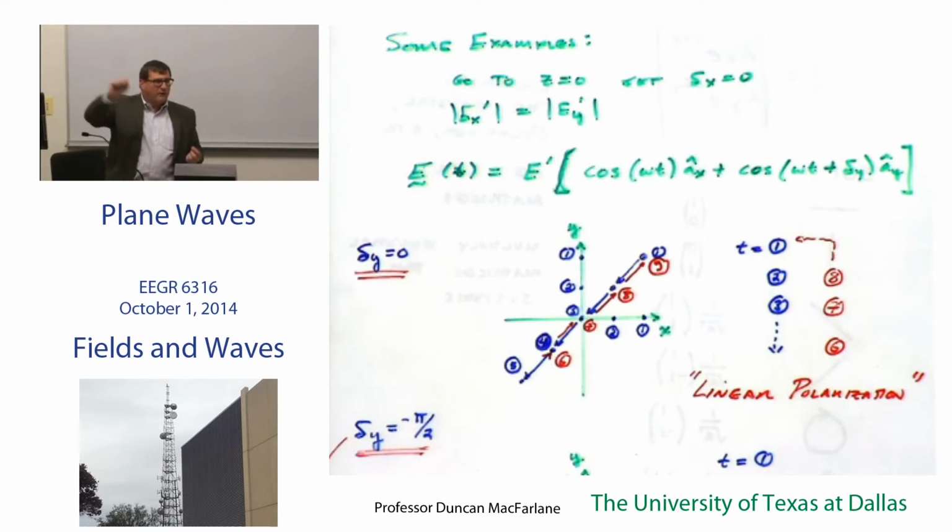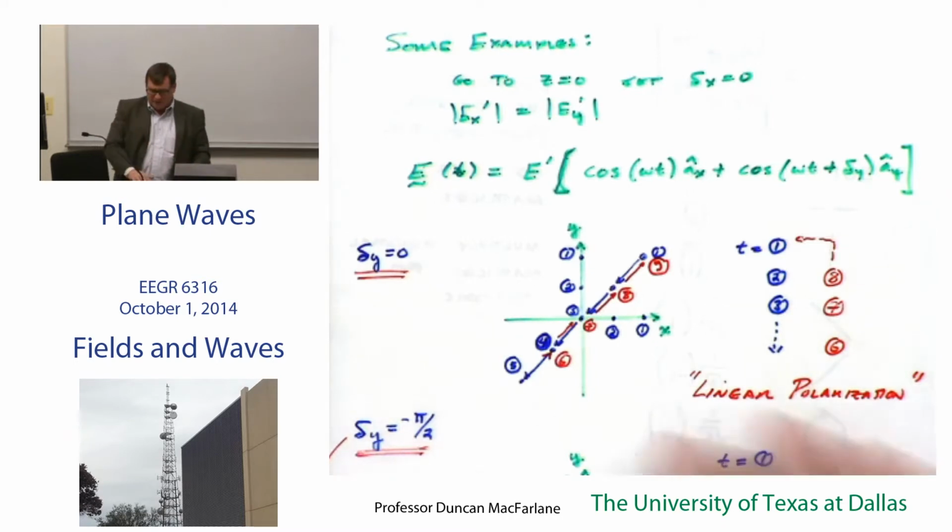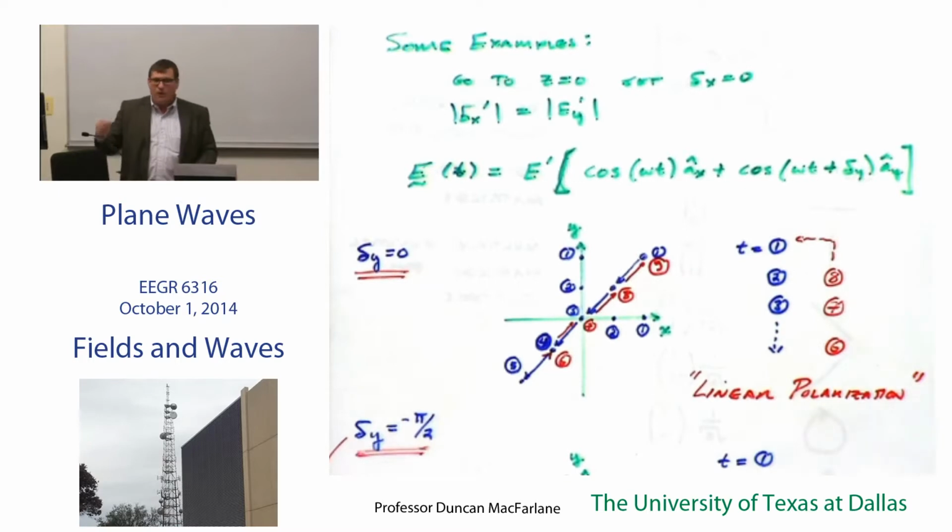So if this were a wire, the electric field would be kicking the electrons on the wire. So if I have my wire this way, my field is this way, my forces on the electron on that wire is not quite as optimal. But if I turn my wire this way and line it up to that, I get a maximum acceleration of my electrons, a maximum transfer of the energy in the field into that wire.